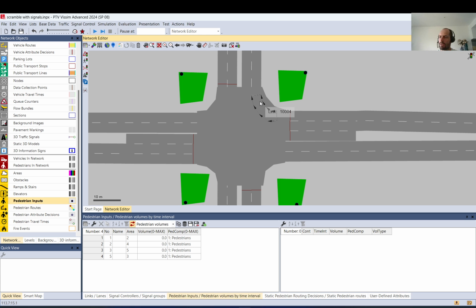If you have pedestrians that consider signals while they are in the intersections, they wouldn't be able to get out of it. So you need to make sure that you only place so-called one-way signals to make sure that they can get in, but even if in the meantime the signal goes red, they can still get out without being blocked.